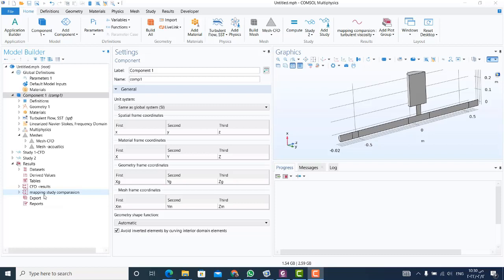After completing the CFD study and connecting between the acoustic mesh and the CFD mesh, we began to make a linearized Navier-Stokes study. So we can see the influence of the fluid flow on the acoustic wave coming from the source here. First we need to set up the acoustic model solving the linearized Navier-Stokes equation for the background mean flow configuration with Mach equal 0.05 and Mach equal 0.1.